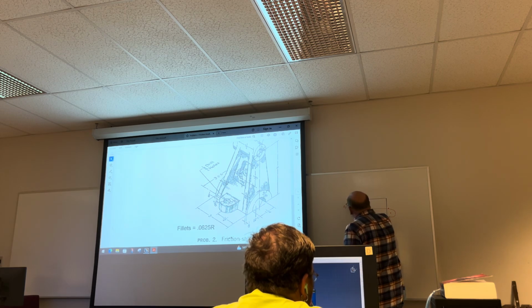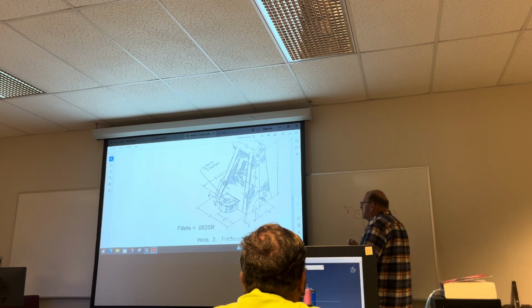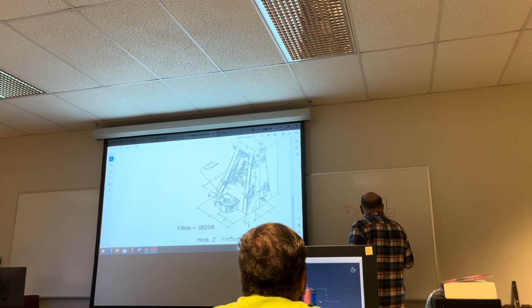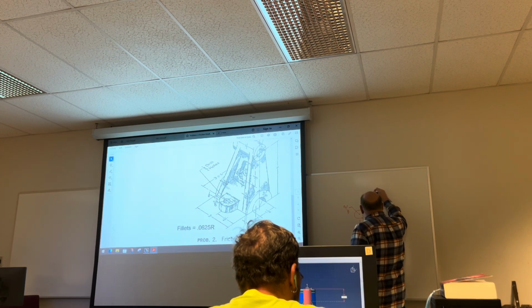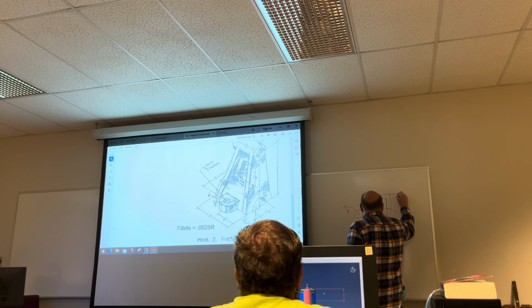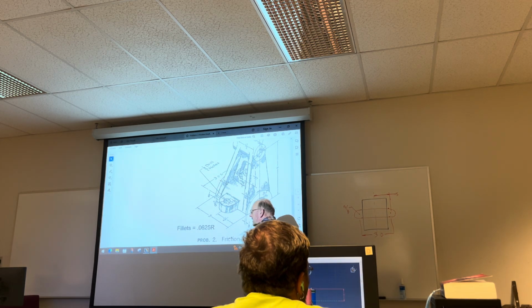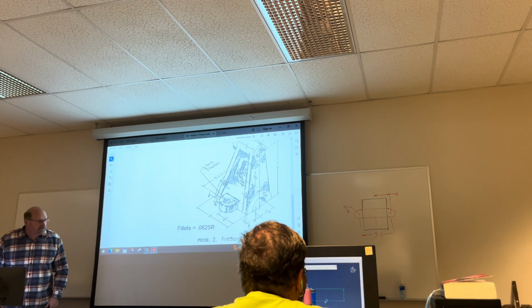All you gotta do is plug those values in, because it tells you the center to center distance, 3. So you come into the sketch and you put this in here, and obviously you'll have your plane here, right? You'll probably have to do a 1.5 from this, maybe something like that. So everything's in the model. Actually, with all the planes and everything, it's real easy to dimension that, because you can dimension off of a plane.